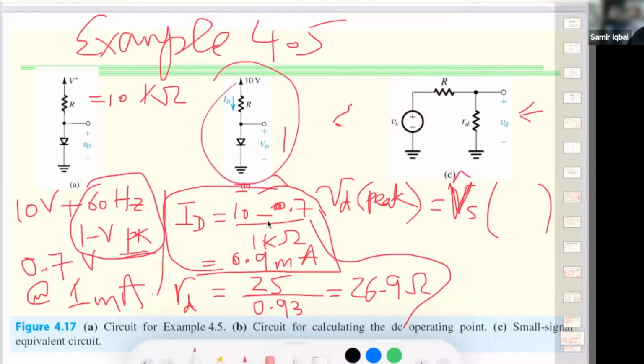So if I have to find the voltage across this, and there are two resistances, and there is a voltage, how do I find it? You take this one divided by the sum of these two. That will give you how much voltage drop is going to occur across the resistance of my interest. That's what I want to find out. So that's the ratio proportion.